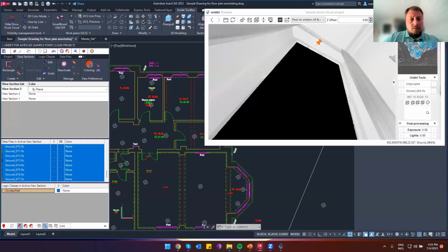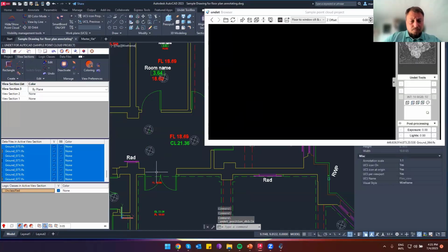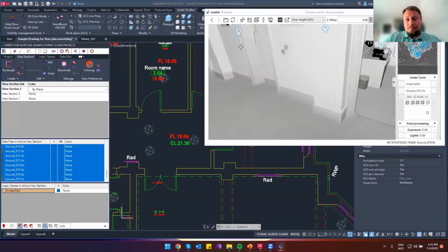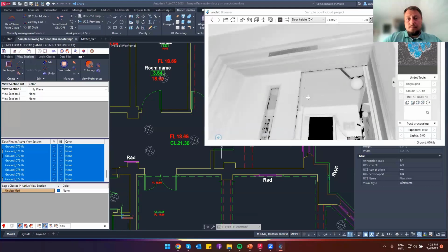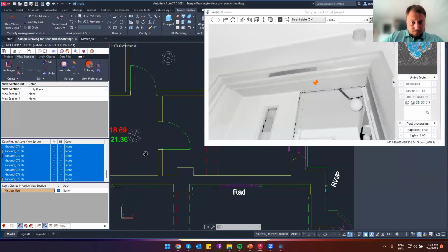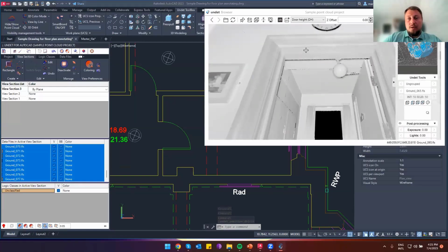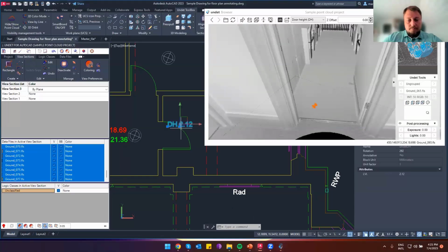And I forgot one more script, for example, annotate door heights. So I'm going inside the scan position next to the doors, and we'll select the script called door height. Okay, so these doors. One click on the floors, doors head, and they have annotation of the doors. The same if I go to another spot. Now you see where the doors are here. You can even first click on the door's head, then on the floors.